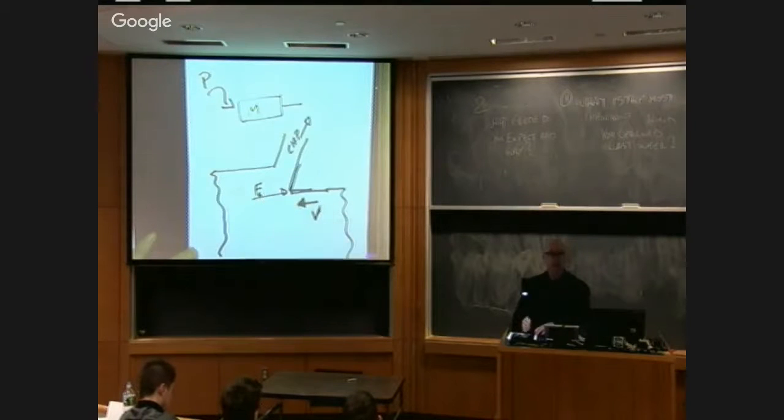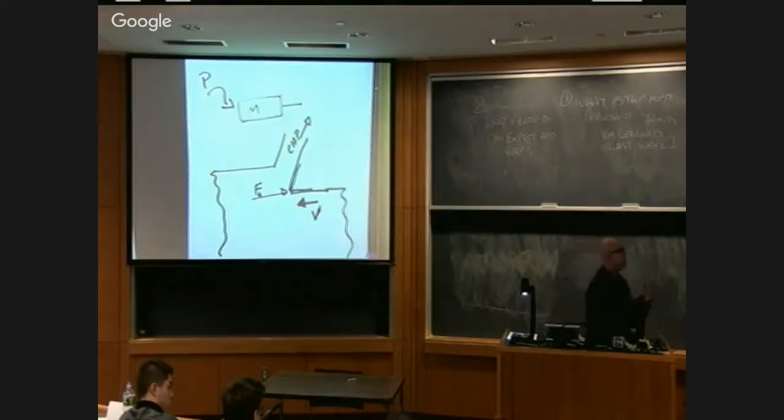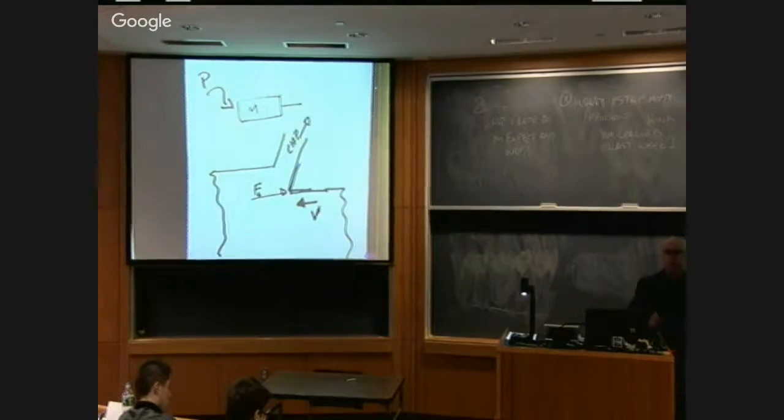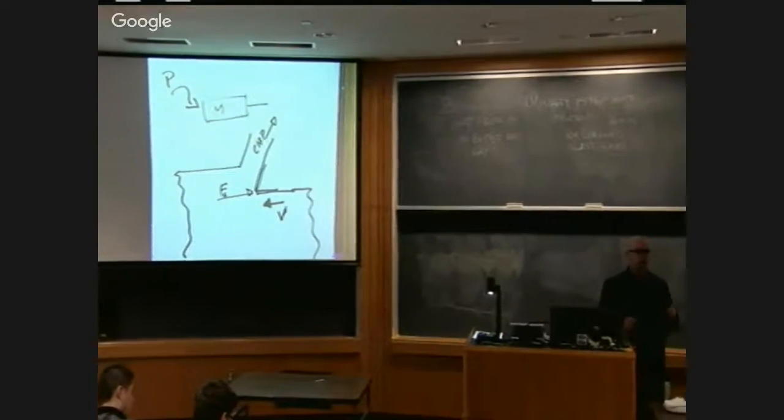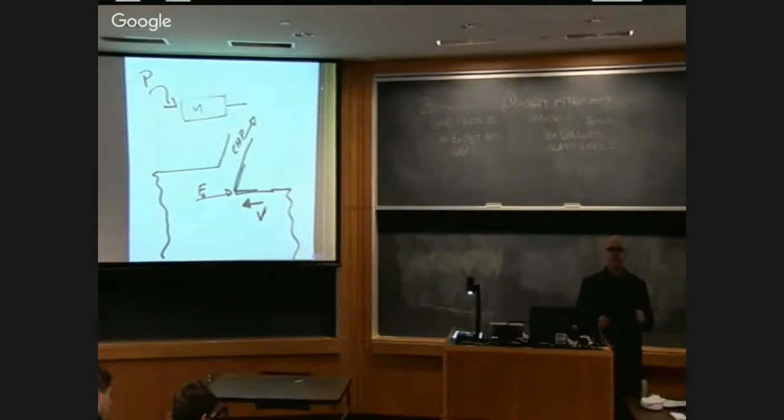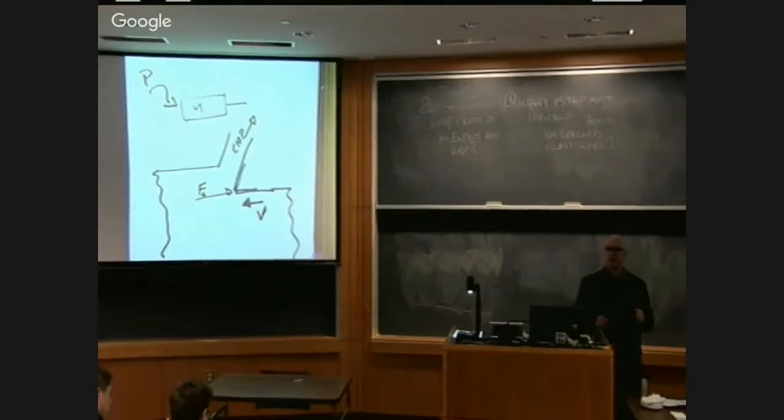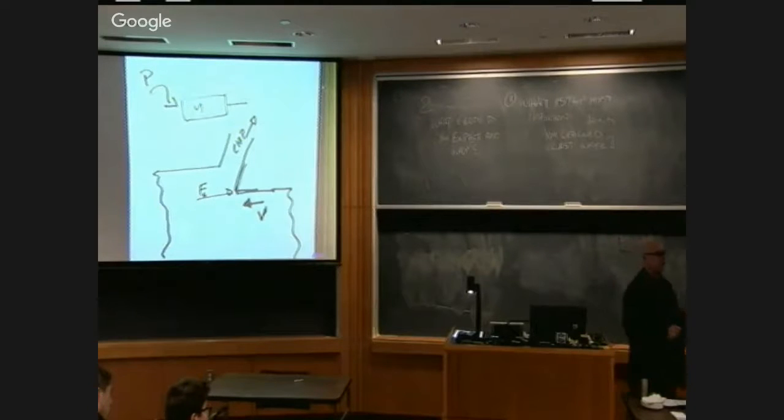We're going to call that FC. That's the cutting force. So we're going to talk about, if we know the velocity, and we know the power, we can calculate the cutting force. That's kind of cool. Why might we want to know the cutting force?